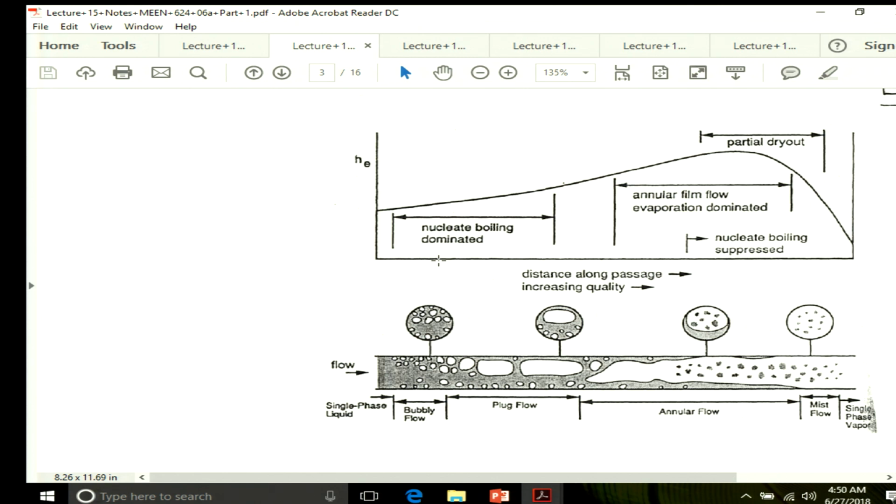So, here because of the added shear, because of these big bubbles moving around, you typically get flow reversal. Oh yeah, that is the other video I wanted to show you, I forgot to show you, I will show it to you after the break. You will see that there is a flow reversal that occurs, where this big vapor bubble moves in this direction, but the liquid starts moving in the opposite direction, and then in the wake of the bubble they again flow back. And all these actually cause the heat transfer coefficient to go up, and right before it